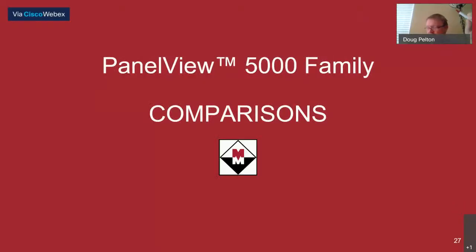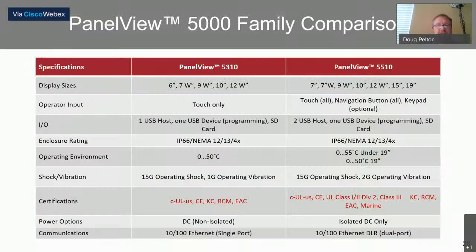Okay, so that went a little bit longer than I planned on going, but we'll talk a little bit about the comparison between the two products. We did talk about the sizes on the PanelView 5310 and 5510, and the differences between them. Operator input: the 5310 is touch only. If you need keypad and navigation, the navigation button is included on the 5510, but you can configure part numbers with a keypad for the 5510 only.